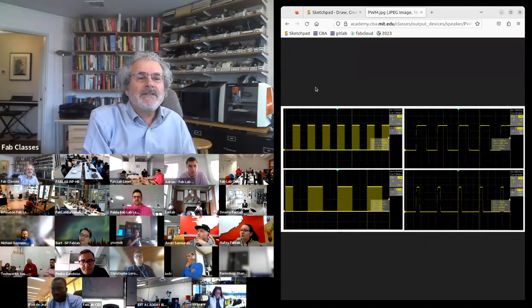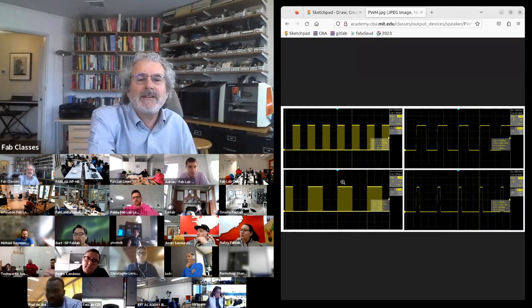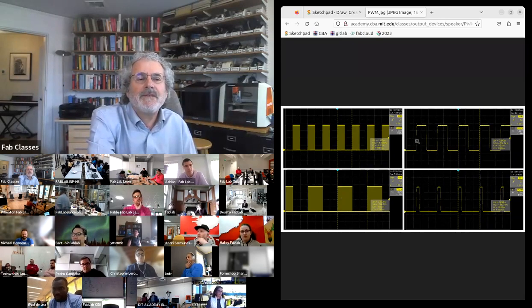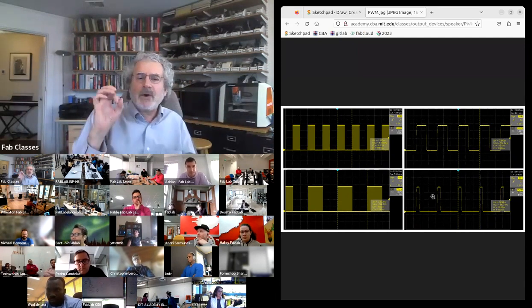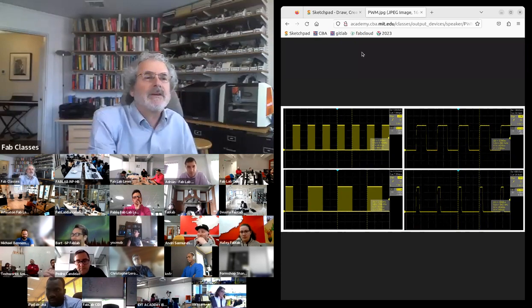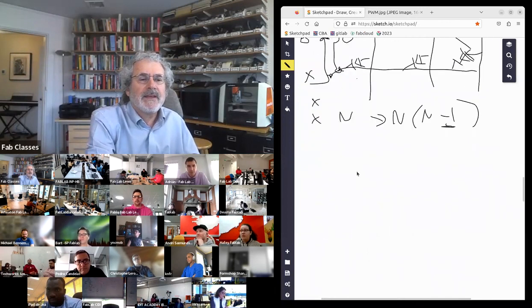And so this is what's going on. To vary the frequency, this is high frequency, this is low frequency. And to vary the volume, I'm varying the on time versus the off time. So I'm putting out pulses to the speaker, and it's slightly confusing in that